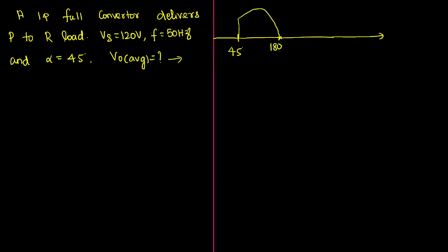That's all. So after 180 degree, once again you must leave a gap of 45 degree. Once again at 225 degree, one more pair of thyristors will take responsibility to produce another waveform. This is, however, the output waveform, which will be discontinuous in the output side.